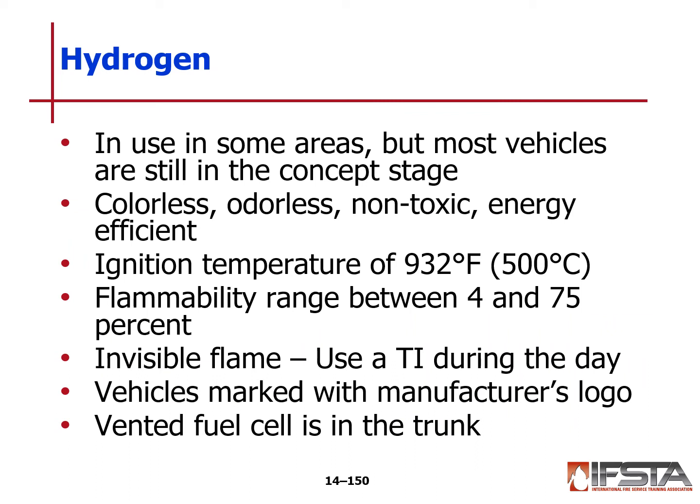Hydrogen is another alternate fuel source that is out there. It is in use in some areas, but most vehicles are still in the concept stage with the hydrogen type fuel. It is colorless, odorless, non-toxic, and energy efficient. The ignition temperature is 932 degrees Fahrenheit, which is fairly high. Flammable range is between 4 and 75%, which is very wide, and it does produce an invisible flame.